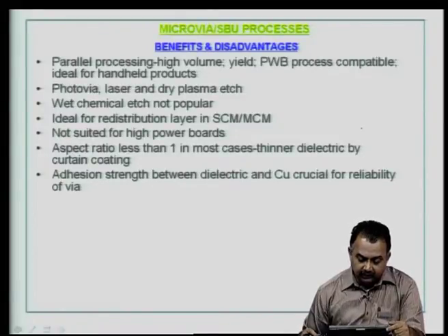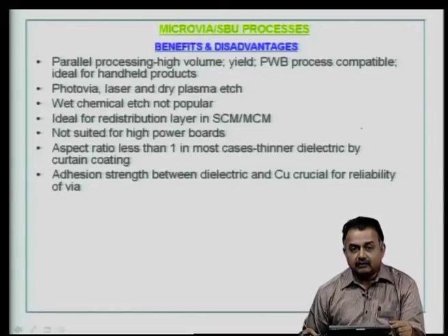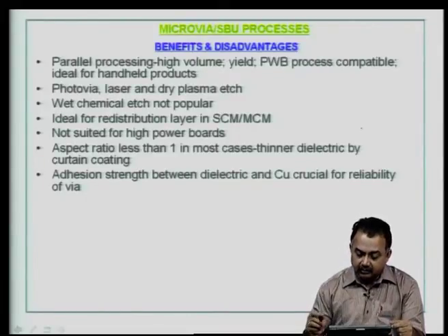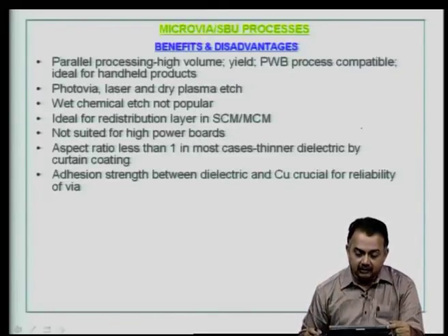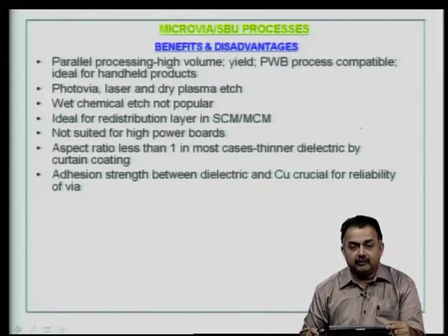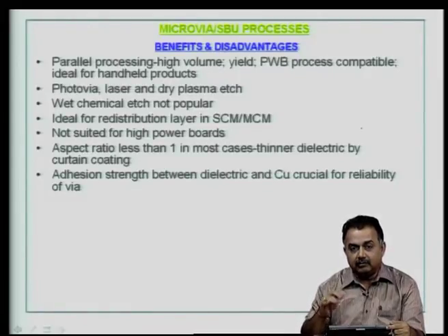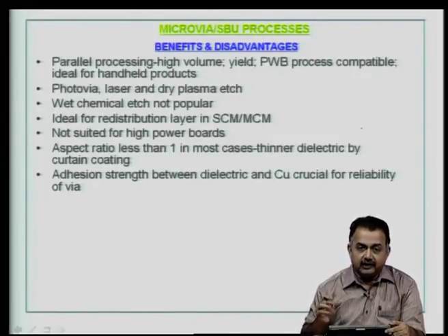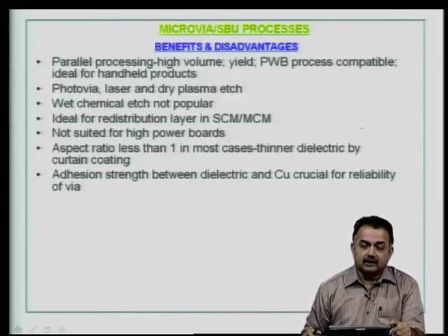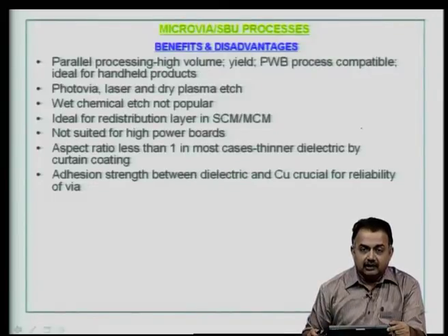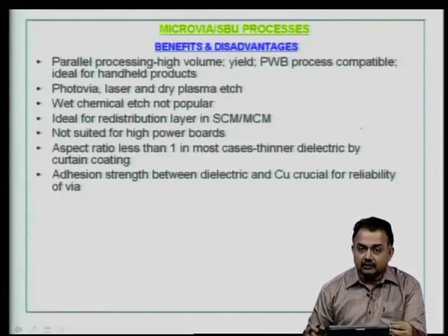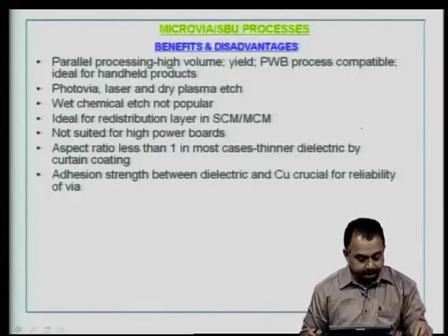Adhesion strength between the dielectric and the copper is crucial for reliability of a microvia, because whenever you create a microvia and then try to do an electroless plating to wet the microvia and establish connection between the top and the bottom layer, you are defining the reliability of the board as such. That is where the crucial functionality in terms of adhesion strength, the peel strength between the copper and the dielectric, plays a major role in the stability of the board and also long shelf life of the board.